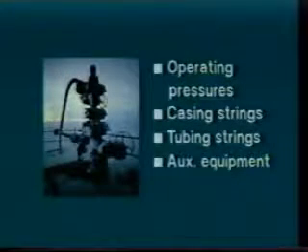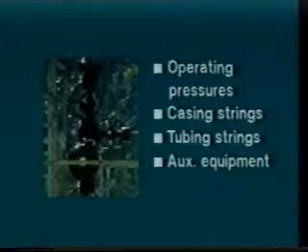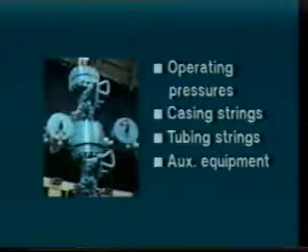Now let's go up to the top of the hole and discuss the wellhead, the piece of equipment that joins the subsurface equipment with the surface equipment. There is no single unique wellhead design, but in every case, the primary purpose is to safely control the flow of fluids under pressure. The design of the entire arrangement depends on the expected operating pressures, the number and sizes of casing strings, the number and sizes of tubing strings, the need for auxiliary equipment such as subsurface safety valves and artificial lift equipment,